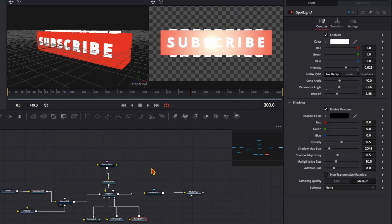Now go to the spotlight, go to frame 0, change the intensity to 0.26 and add a keyframe by clicking on this diamond. And next go to the last frame of the animation and change the intensity to 0.88. This will automatically add another keyframe.